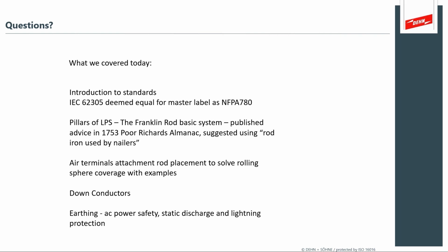Yeah, it kind of comes back to the question about the vent of a HVAC system as well. If you bond these vents or these HVAC ducting together with your LPS components, you run the risk of injecting lightning current into the structure itself. So this is a risk that you need to determine. Is it acceptable for you to inject current that way? If not, you have to maintain that separation distance away from these vents and these HVAC ducting, and make sure that lightning current stays separate away from it, and then provide air terminals that are higher than these vents to create a zone of protection over these vents rather than installing a terminal on these vents.